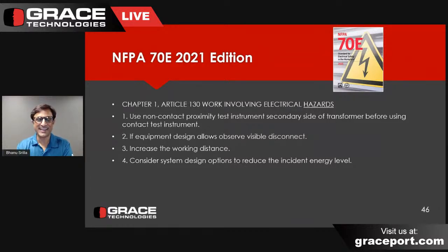So Terry, I want to just make a quick comment, right? I was in NFPA training last week on 70E, the new standards, and there was this topic. People think that when it comes to PPE, there are only two: one is a 12 cal, one is a 40 cal. There's nothing in between. There's nothing over. That was because the hazard risk category said minimum 40, but the word is minimum. And then the arc flash PPE vendors flogged HRC 2 and 4 kits and unfortunately boxed the industry in.